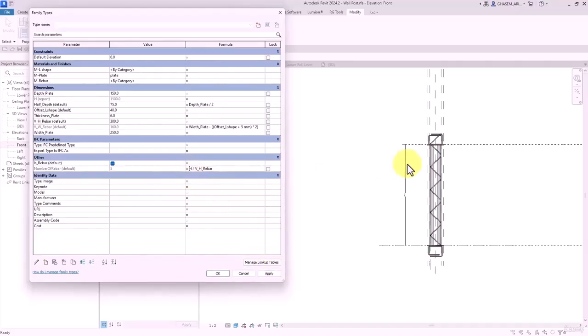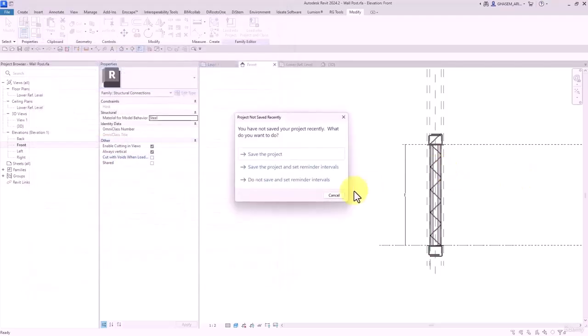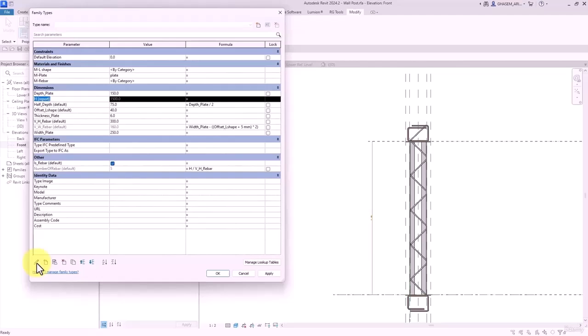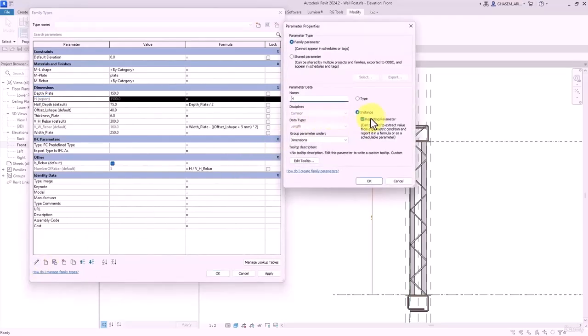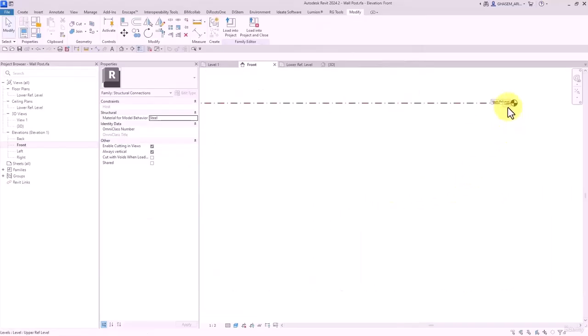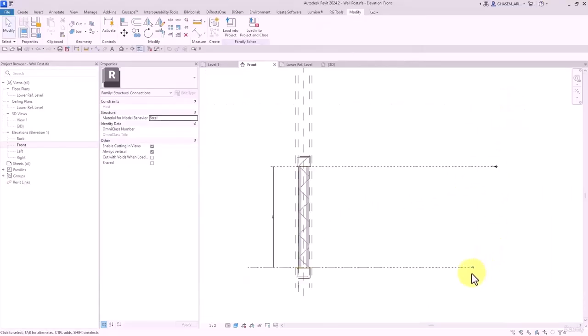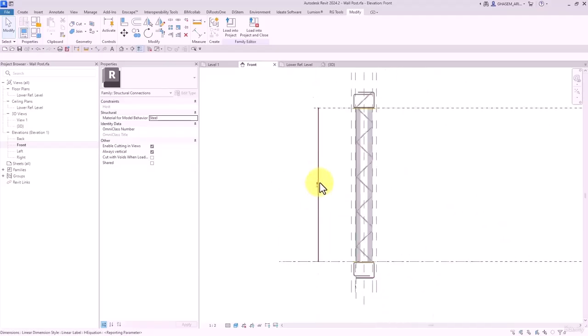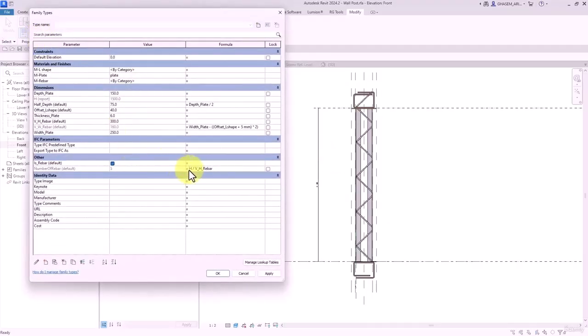Okay. Then here. Why I did this? First of all, this parameter is not editable and it will be reported automatically. When I deselect this, I'll face a warning or error because this family which I open contains an upper level and lower level, and it can only change according to these two. And we made this to have information and use it. That's it.